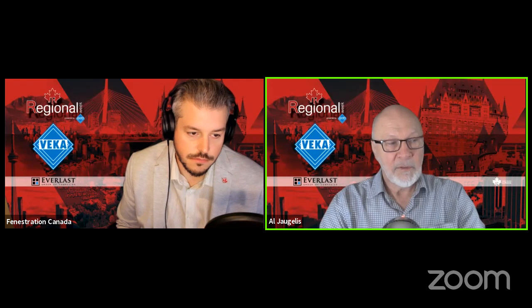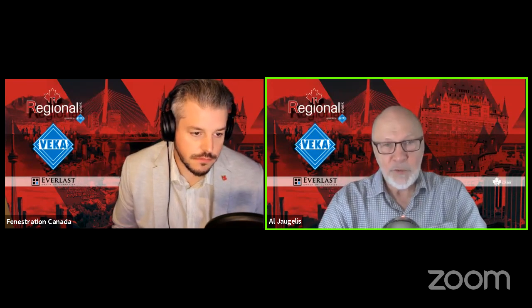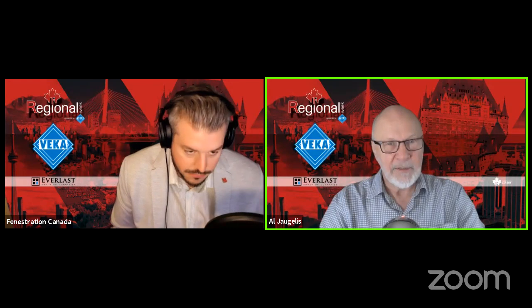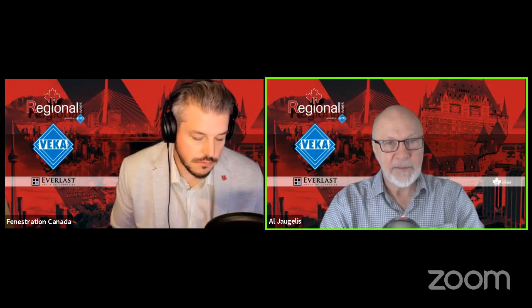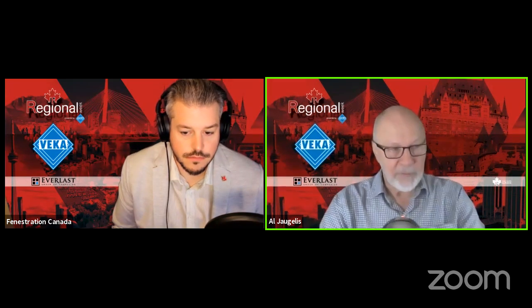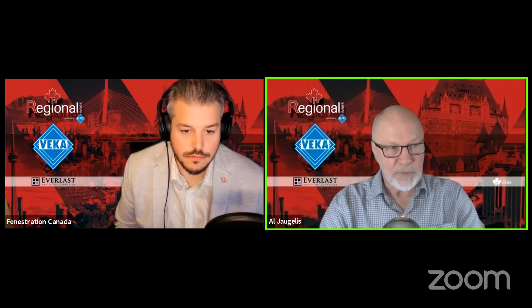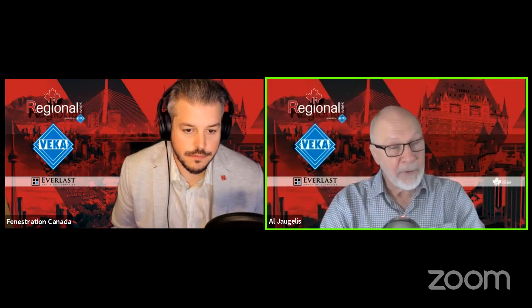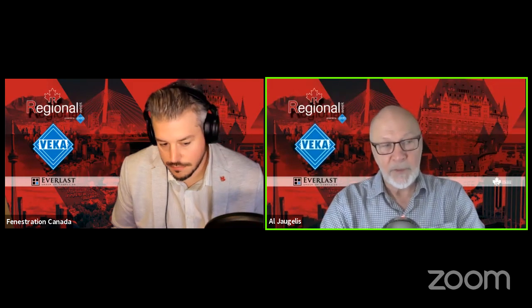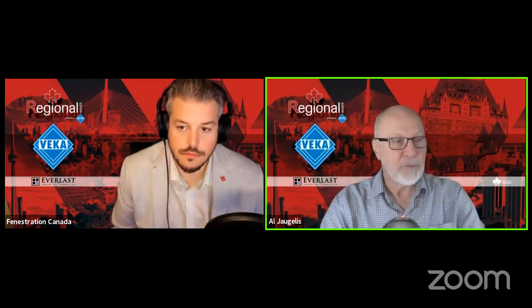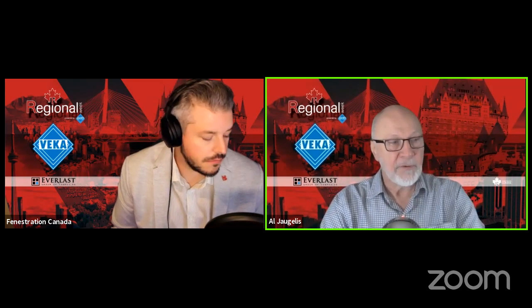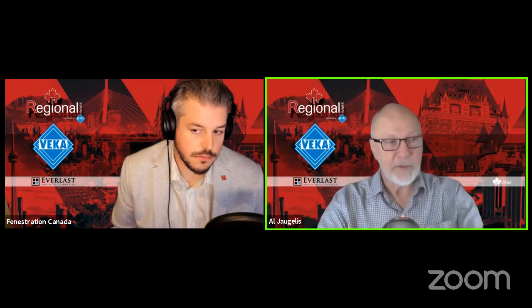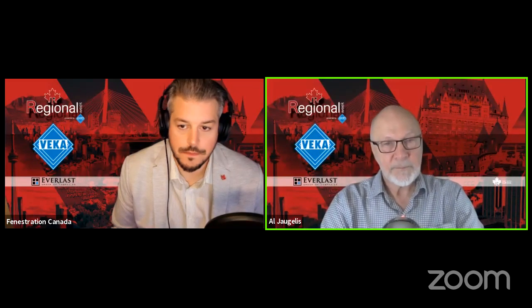And the 2015 National Building Code says you can't expect those doors to be watertight. They are exempted from air and water tightness requirements. Okay. So it's perfectly clear. NAFS does not apply to those doors. The code also tells you you can't expect those doors to perform as effective air and water barriers. You have to use other measures to deal with whatever air leakage or water penetration those doors might experience. As an architect, you need to deal with that in other ways, rather than expecting it to perform like an environmental separation fenestration product.